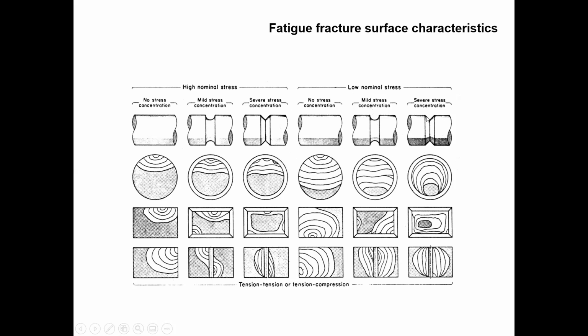But you can see this is very sharp, severe stress concentration. Then you can see the failure. So you can see the failure cross-sectional variation, but this is below the endurance limit. Assume not too much below, but very close to the endurance limit.